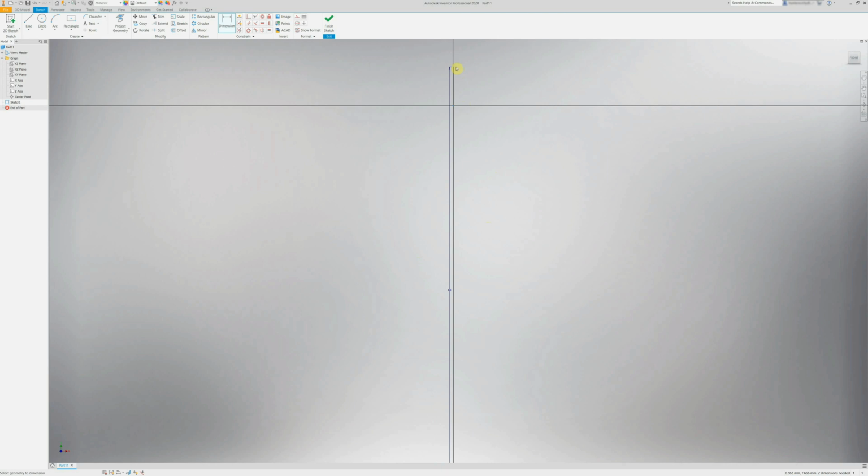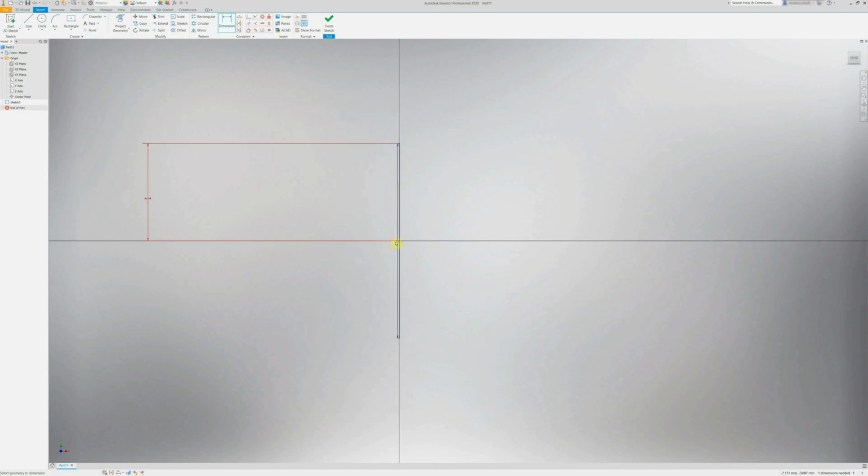So I'm just going to take from the center origin to one end of the line, and I can either type in 44mm here to budge the line up to center, or I'm just going to select that first dimension, 88, which is called D0, and divide it by 2. That will keep this center line always in the middle, which can make things really useful later on. So say, for instance, I change the size of this and made it 100, it will automatically adjust that dimension to 50mm, keeping it nice and centered. In this case, I need it to be 88, so there we go.